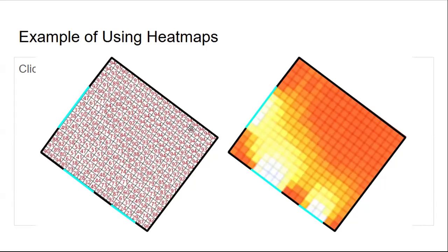All right, so 94%. And right here is 95, so it's still very red or orange-ish. But if it goes to the middle, because those areas are very close to the window, it's 47, 39, which means 39% of the time in the year, this area falls into the 100 to 3000 lux range. And it is right next to the window, so it is not hard to imagine that the rest of the time, most of the time, it is over-illuminated. That's why it has this whitish color. So this heat map helps us to understand the numeric values better. That's why it's often used.